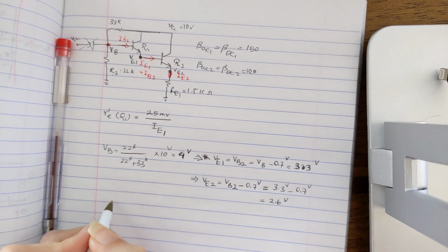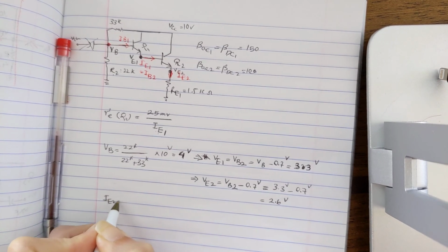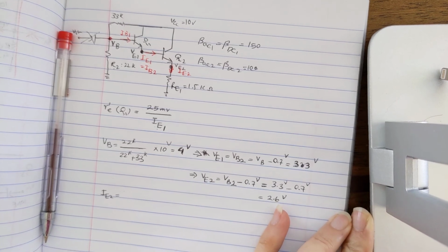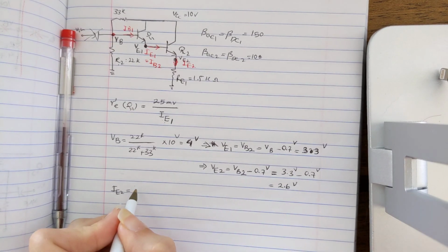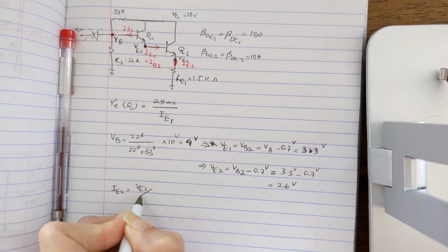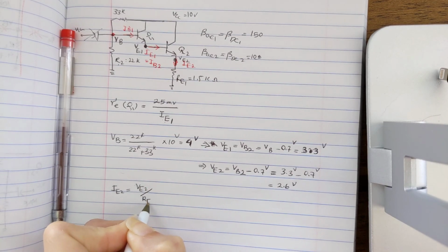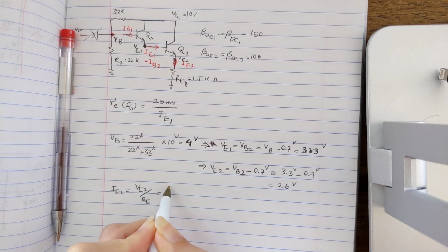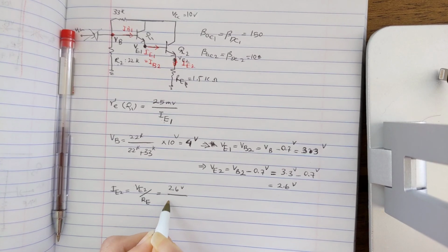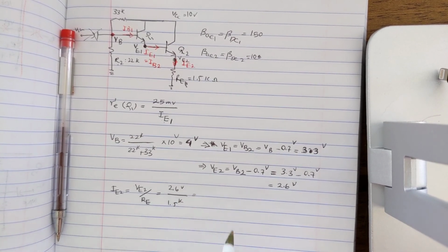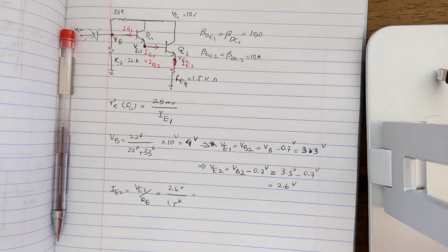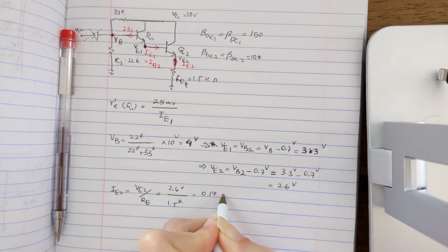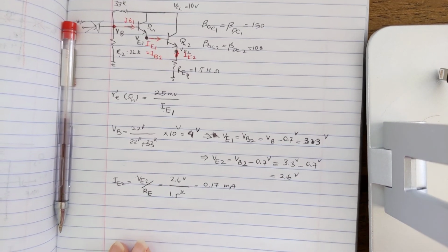Now, based on Ohm's law, IE2 is going to be VE2 over RE, which is 2.6 volt over 1.5 kilo ohm. So 2.6 over 1.5, it's going to be 1.7 milliamp. Now, if we want to